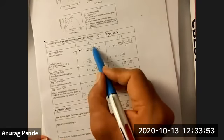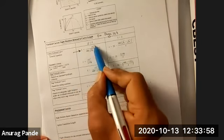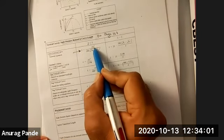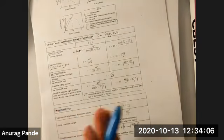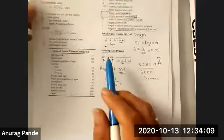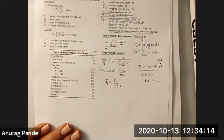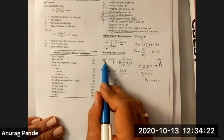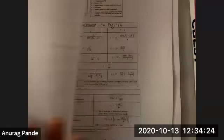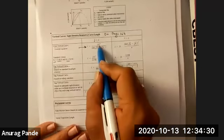So obviously, as the stopping sight distance increases, what happens to the L value? It's an empirical formula that changes by a factor of S squared. So as you increase the stopping sight distance, which you can obtain using this formula, be careful and take a look at the problem carefully, because in some cases the problem might specify that value. So you can either get that value from this formula based on the design speed, or from the given problem. That's S, the stopping sight distance.